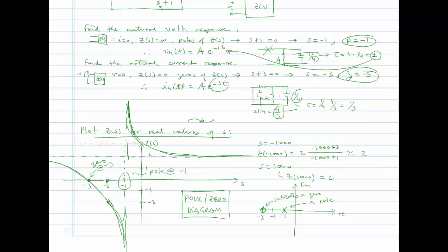Now think about this network. If I'm at 0 frequency, then this cap here is an open circuit, right? And the only thing that I would have at 0 would be 2 plus 4 ohms. Although I didn't show it on here, I didn't draw it to scale. This at 0 should be equal to 6 ohms, right? 2 plus 4 is equal to 6 ohms.